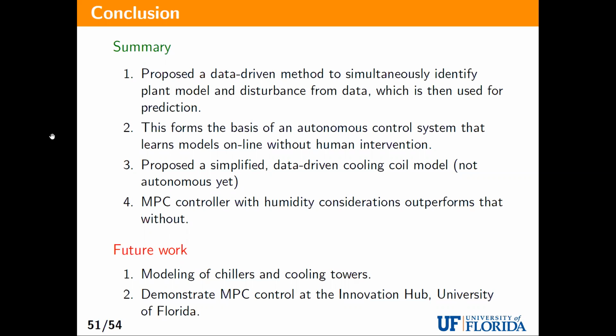Now we're not completely there because for some of the equipment models we are still not able to get linear models that give us the performance that we need. So we are struggling with that. And the MPC controller with humidity, again, given that we are in a dry climate, this may not be a super important comment here, but in Florida, it is really important to have humidity in your problem formulation. Although it makes the problem more complicated, if you don't do that, then you'll seriously screw up.